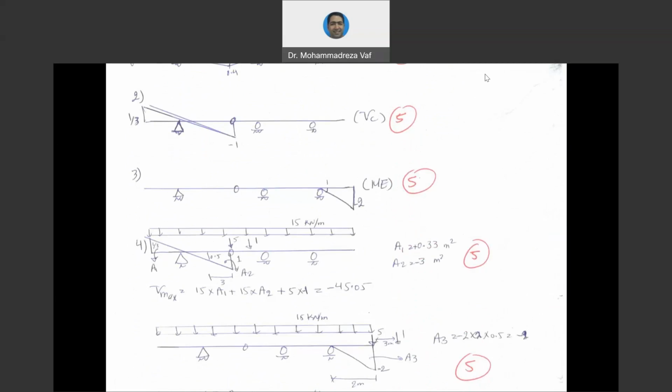Another scenario that you can also examine is the case where we have 1 ton here and the 5 ton is 3 meters behind it, where the value of the influence line is 0.5. So 3 multiplied by 0.5 is 1.5, and 1 multiplied by 1 is 1. It gives us 2.5. So this -2.5 is smaller than -5. Therefore, this scenario is going to provide the larger shear force, and the first one is not the critical one.